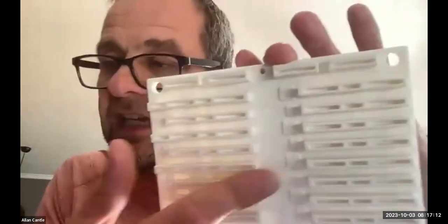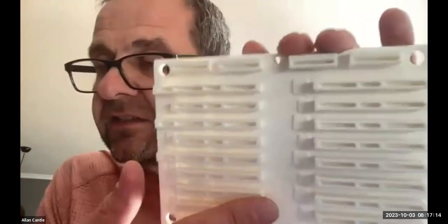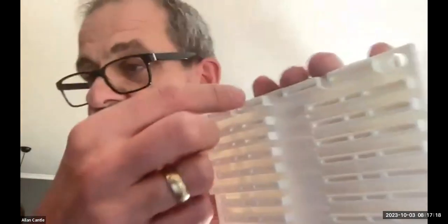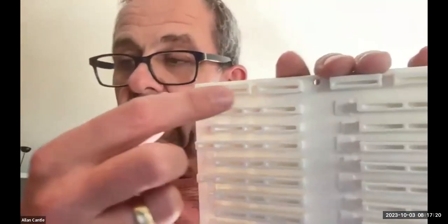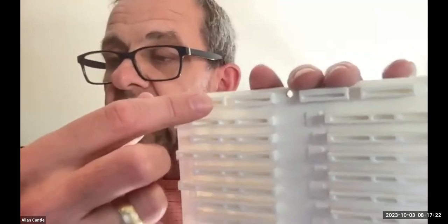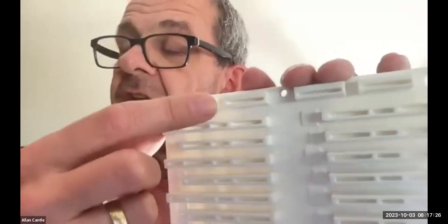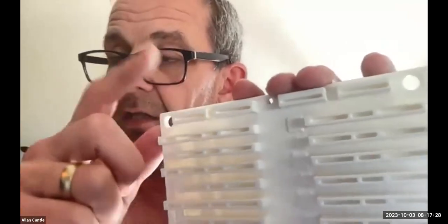These are standard TE, or no, originally the TA1002 connectors, EDSFF, and these ones on the edge here are currently MCIO, the new PCI connector, but they equally could be some alternative Ethernet connectors as well.